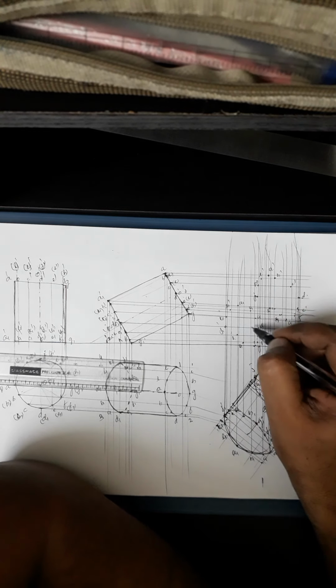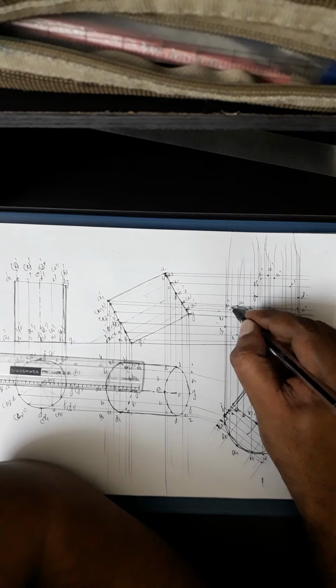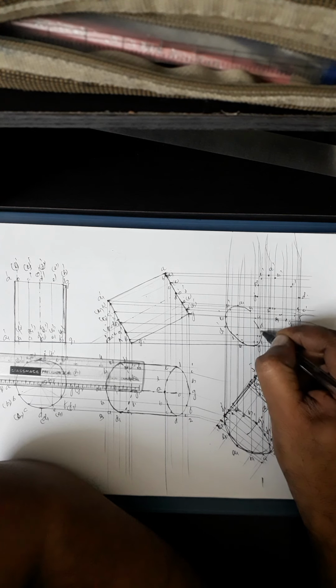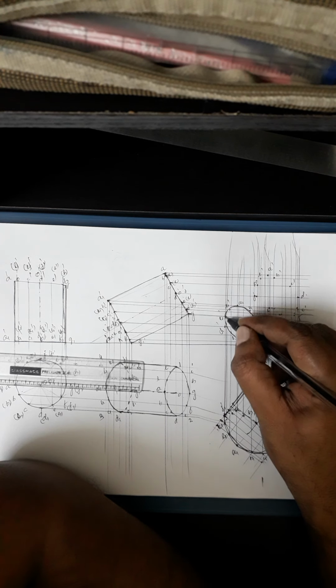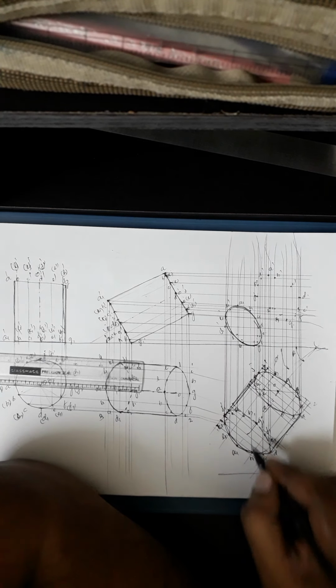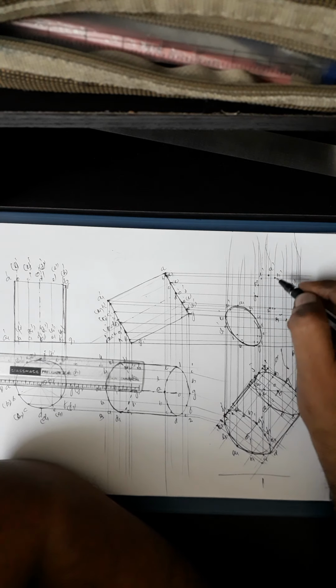So all dashes. Okay. So now when you look at from here, the base is visible. That's why all these projectors and locii should be very, very thin. Otherwise you will not get the view properly. You cannot make out the view. So go for drawing with a thick line, because this is the visible end face, because that is nearer to me, O1 compared to O. So this end is visible.